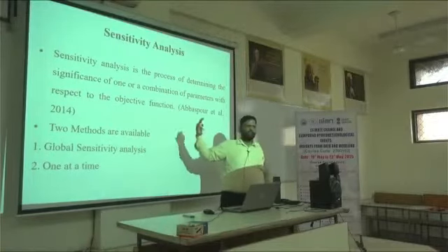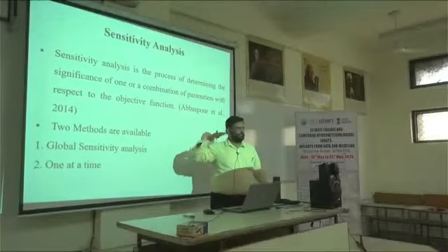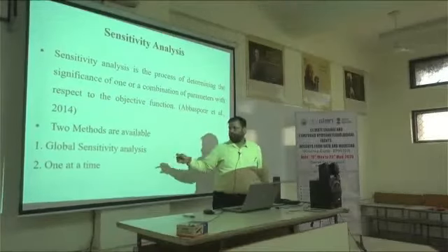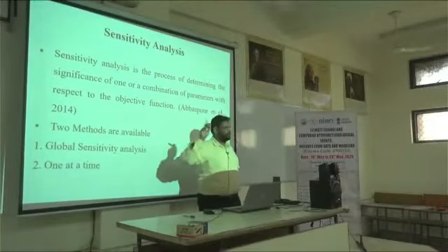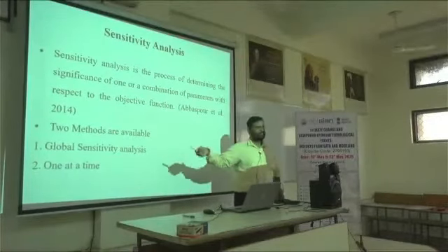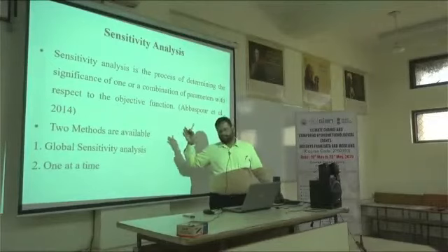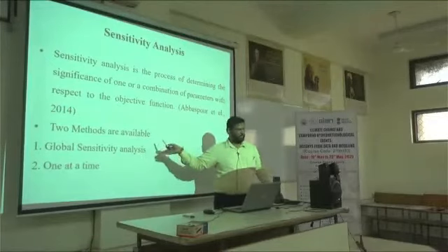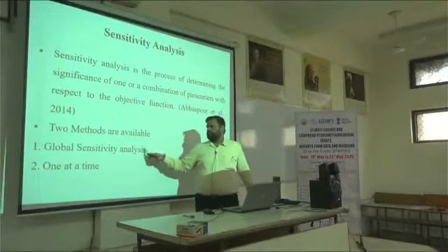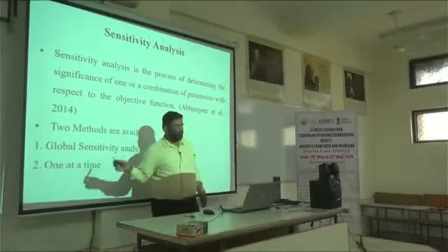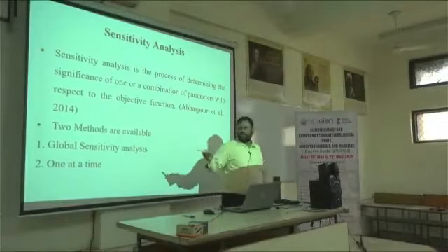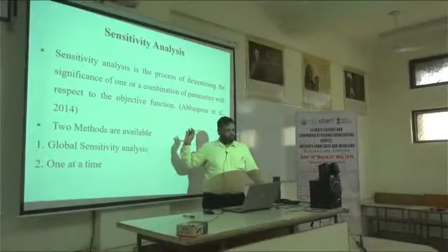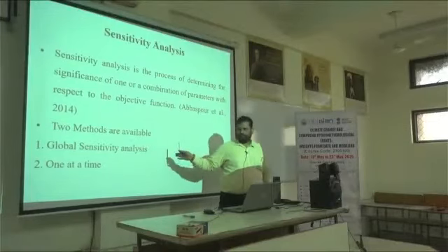Like for discharge, 30-40 parameters, we can give all of them, and we use some statistical method like the t-stat or t-student method or p-stat method. With the help of that, it will compute. Some optimization techniques are also there. Then it will give which parameters are sensitive for your watershed.